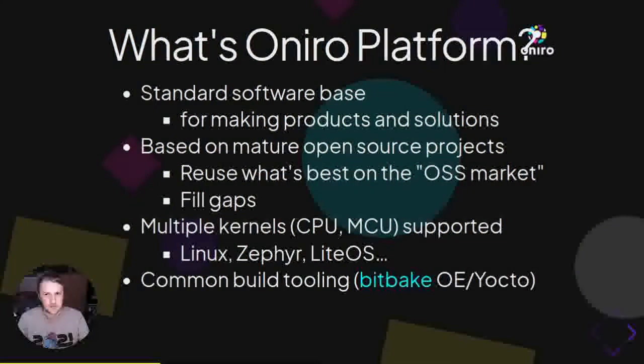Anyway, even if we are working on different devices, there are a lot of things that can be factorized. For instance, the way to build firmware. We can reuse a build system from OpenEmbedded and Yocto, which is based on BitBake. That's a tool maybe you already know, and it can also be reused for supporting other operating systems. That's convenient. If it works well, there is no need not to use it.